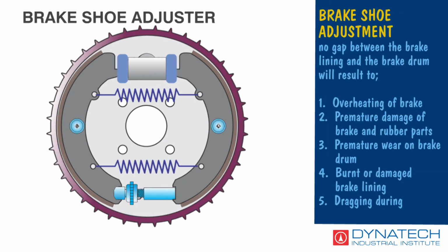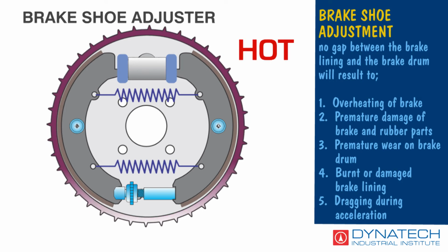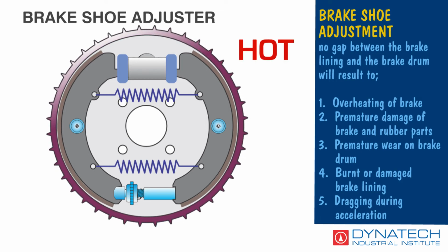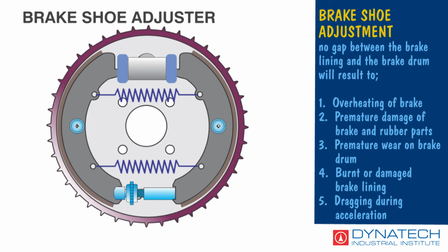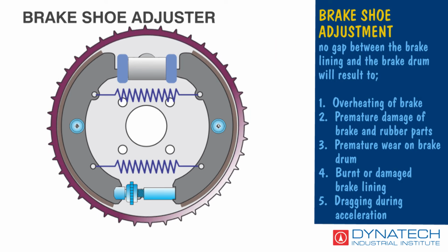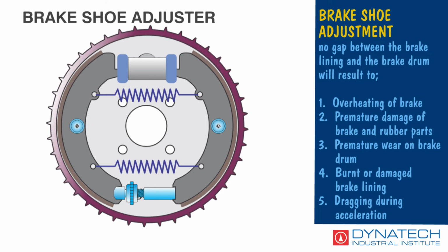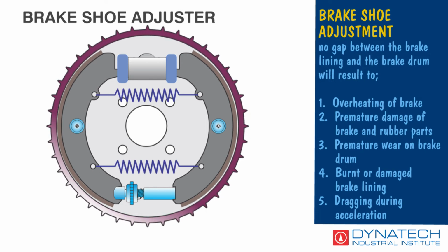No gap between the brake lining and the brake drum will result in: 1. Overheating of the brake, 2. Premature damage of brake and rubber parts, 3. Premature wear on the brake drum, 4. Burnt or damaged brake lining, 5. Dragging during acceleration.